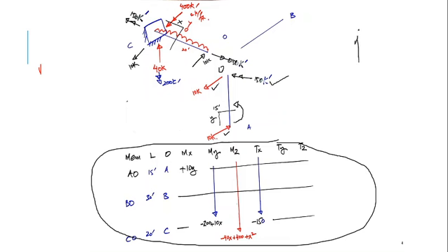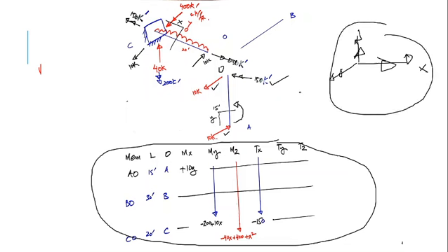You should know that this is anti-clockwise in Y, this is anti-clockwise in Z, this is anti-clockwise in the x direction. Analyzing this frame of reference, I realized that this is 150 kip foot in the x direction, and that is positive because this is forming an anti-clockwise moment.